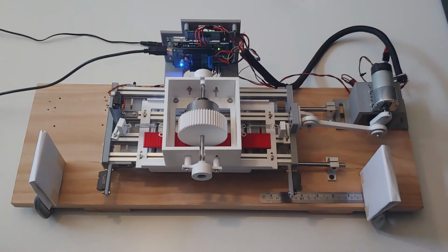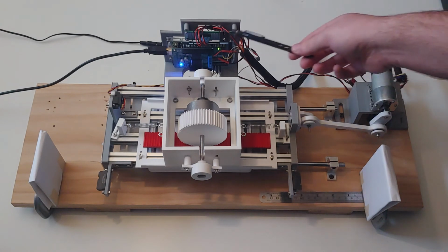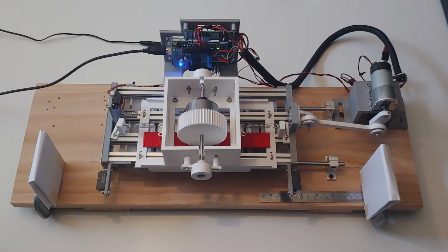The circuit is mounted to the shake table, which allows for minimum movement of the wires connecting the sensors to the microcontroller. This reduces the noise present in the final signal. All of this is powered by a 12-volt DC power supply. This top circuit here will regulate that 12 volts down to 5 volts to be able to power all of our sensors, as well as the motor is powered by the 12-volt signal as well.